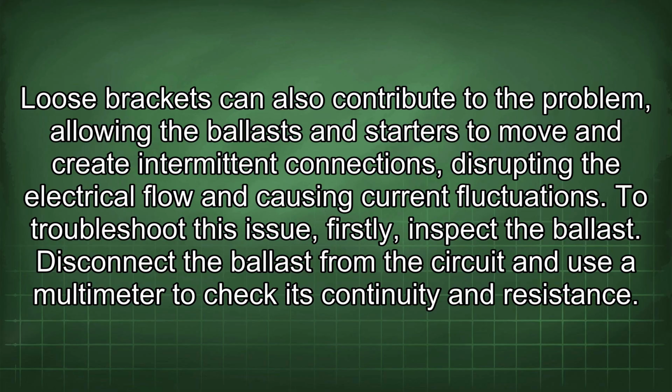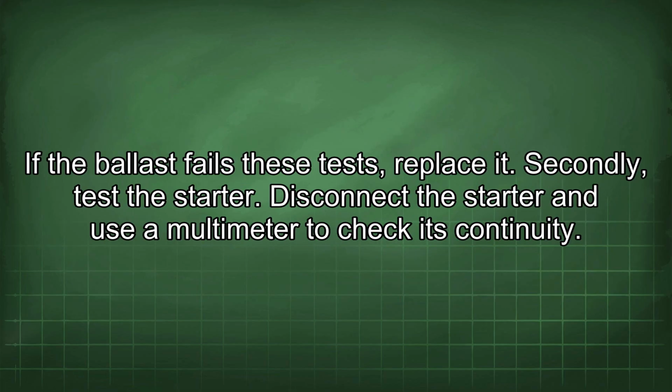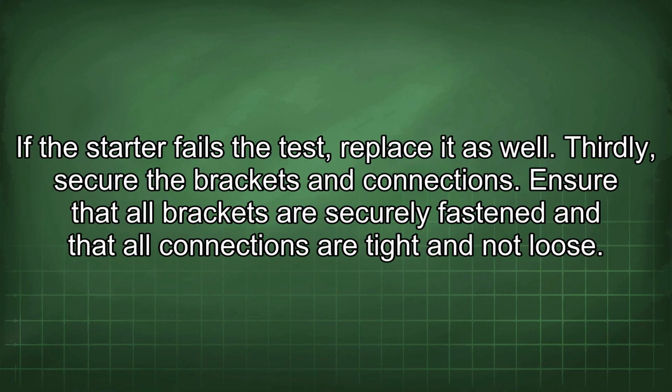To troubleshoot this issue, firstly inspect the ballast. Disconnect the ballast from the circuit and use a multimeter to check its continuity and resistance. If the ballast fails these tests, replace it. Secondly, test the starter. Disconnect the starter and use a multimeter to check its continuity. If the starter fails the test, replace it as well.